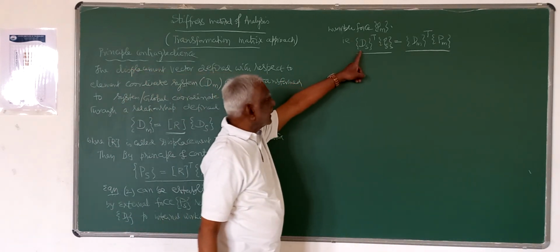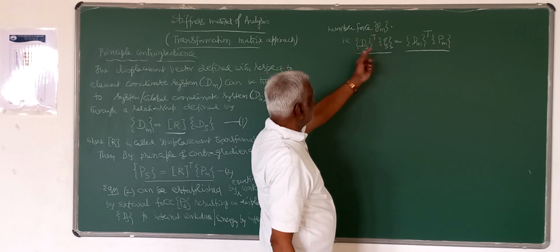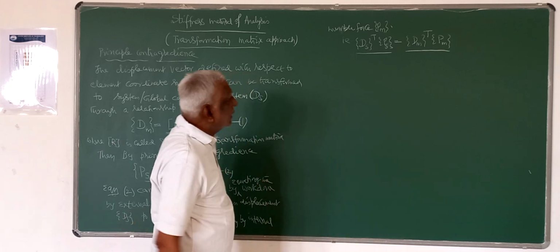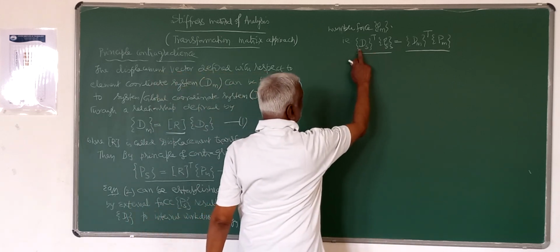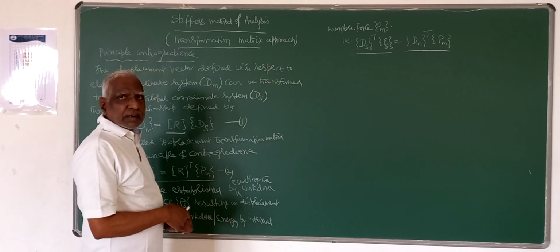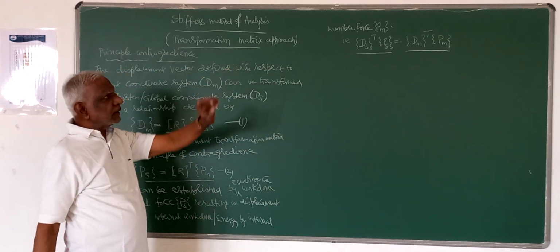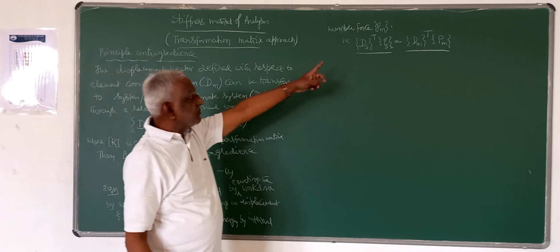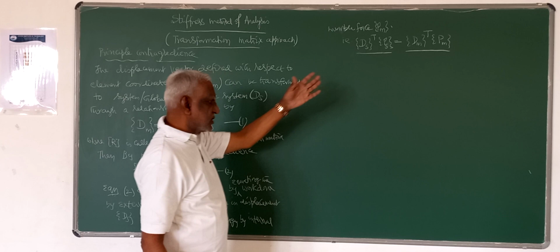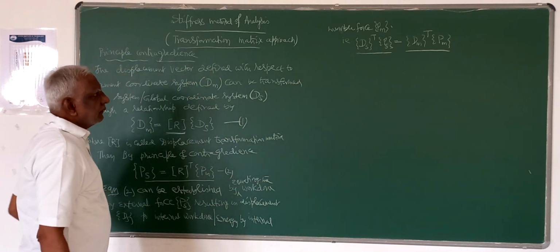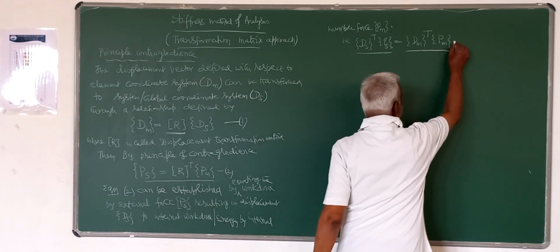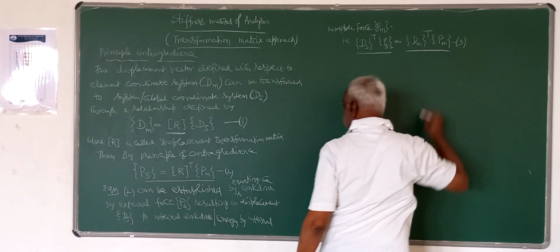Why we are using dx transpose: both dx and Ps are of the same order. When multiplying two matrices of the same order, one should be the transpose of the other, then only is multiplication possible. That's why we write dx transpose Ps is equal to dm transpose Pm. This you have already seen in the flexibility method also. You can call it the third equation.